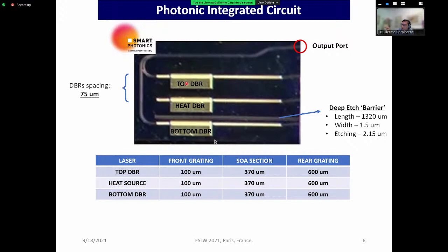Actually, one of the issues that we have to consider as well is that when we are testing these devices, we usually place the aluminum nitride on top of the copper chuck to which the Peltier is attached, but we don't use any thermal conductor, because any thermal conductor will make restoring these chips difficult. So that's something we also have to consider in the analysis.